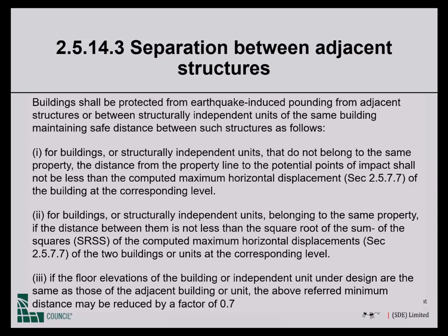And in the judgment of ASCE 7, if the separation distance is the statistical sum of the computed deflections, then the damage would be not unacceptable.